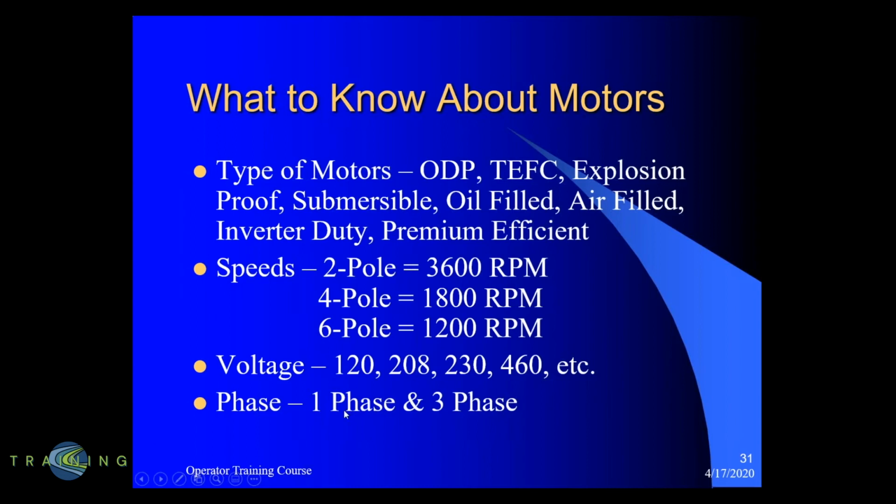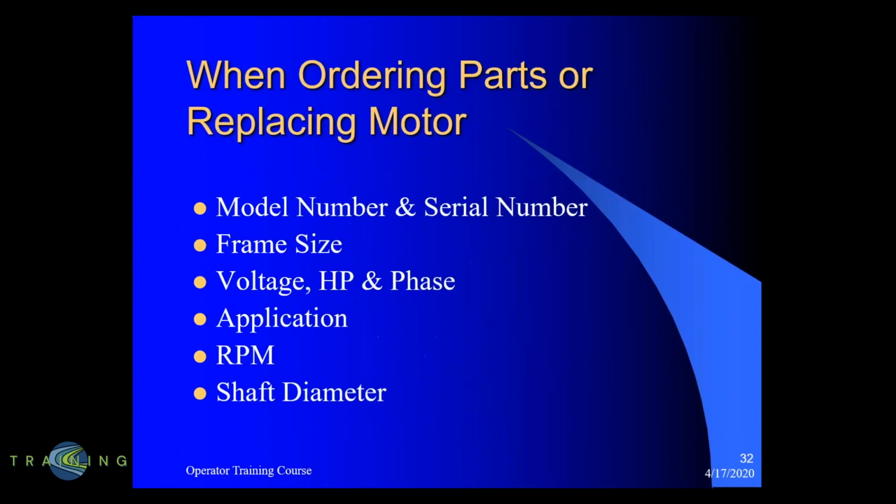We just see it very rarely, but it's very important to know what phase and what voltage we're operating on. When we're ordering pumps or parts and replacing motors, it's important that we get the model number and the serial number off of the motor tag.